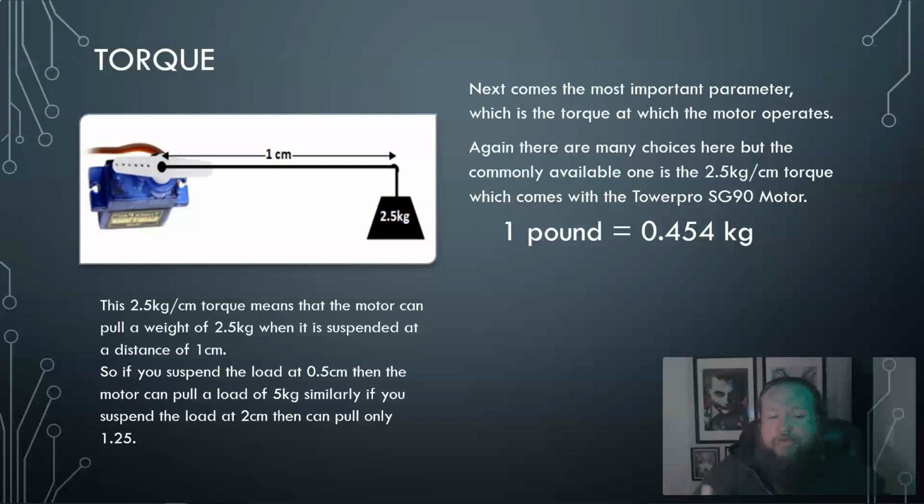So this is part of what you want to look up: if I'm building it, and I know what it's attached to, I then maybe should know roughly the measurement of the actual torque of moving that component or whatever weight it's on, and is that within the tolerance of the servo I'm working with, and maybe if it isn't, I should go to a different servo. For right now, we're just going to get the arm to move back and forth, so you're not worried about that. I would suggest even attaching very basic things to it, but don't go crazy. Don't break the one servo you have, or you'll be ordering another one if you want to work with them.